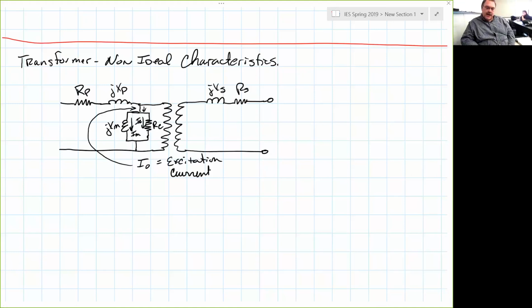And concerning the magnetization branch or the excitation branch, I just want you to know what each of those components are. I think the book might go through a couple of calculations, but we're not going to do a lot. If we had a machines class, we would do a few more of these. But when it comes to practical industrial electrical distribution systems, I think it's important to know the series components. What we're looking at right now are the parallel components, or the shunt components. And I'll tell you in a minute why we can ignore them.